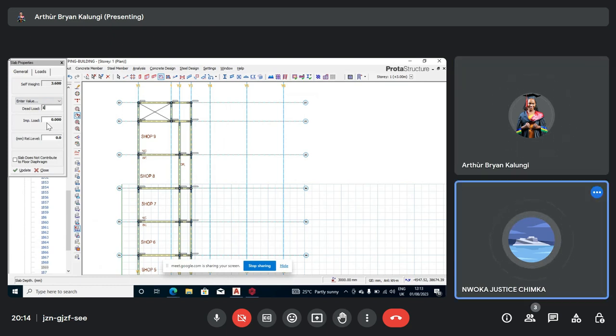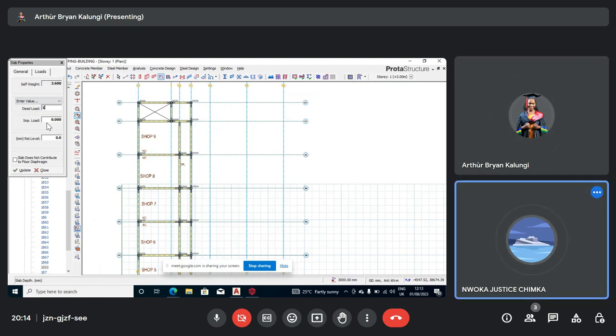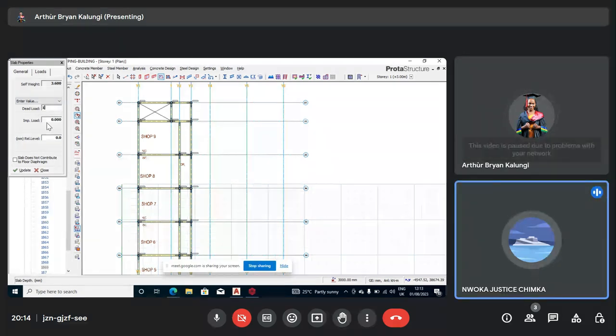Now, the way to select the finishing load is this: if you look at a building like the White House in the US, you can see that the building has so many designs, like all these exterior designs, cladding around the windows, all this fanciful stuff, right? With that kind of building, that kind of design, it is good to use 1.5 or 2.0 as your finishing load.